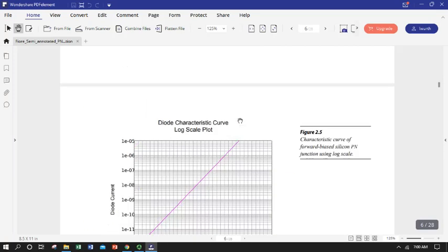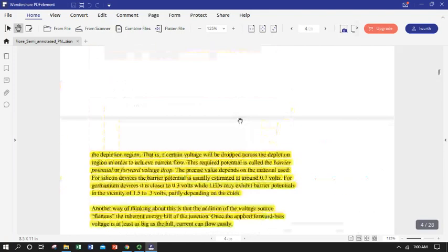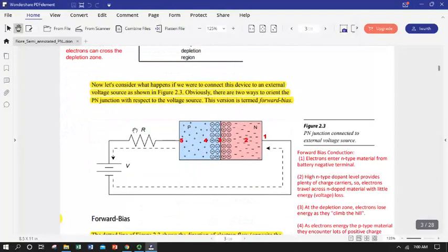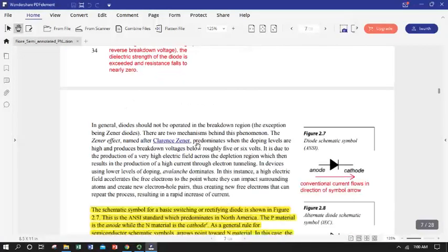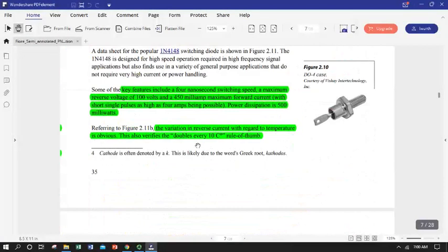And in fact, that's the role of this current limiting resistor. I'm doing a lot of scrolling. It makes sure that the current through our diode does not exceed that forward max, or you'll get the diode too hot and it won't function right.